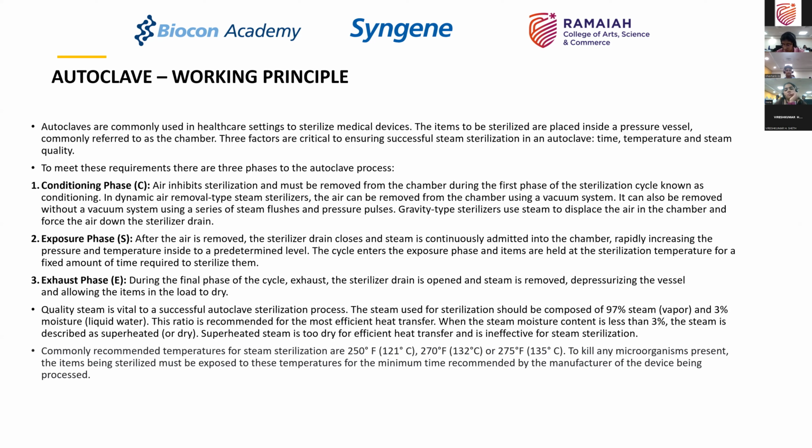Quality of steam is vital to the success. So we have seen that it has to be saturated. In true definitions, 97% steam and 3% moisture is a recommended ratio for heat transfer. When steam moisture content is less than 3%, it is normally referred to as superheated steam. But in general industry terms, you might have a ratio of moisture slightly higher than 3%. In such a situation, you need to look at the steam tables and increase the temperature, or change the conditions at which you do sterilization, so that you achieve the effective kill rate of 10 to the power of -6.